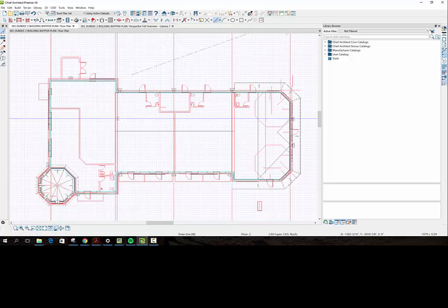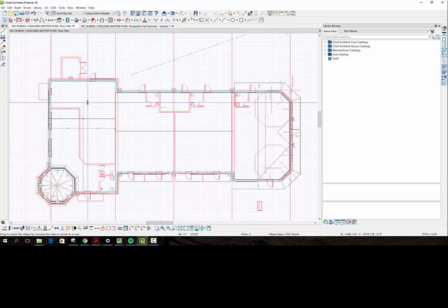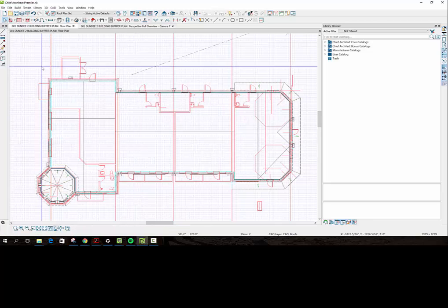So our truss is going to span from this to this. So we'll draw a line there. And that's the length of the truss. And we snapped it. See the snapping tools, Chief's snapping tools saying, yeah, you're here, buddy. And now we'll draw another line. And it should find the midpoint. That triangle's the midpoint. So that's the high point. So see, without dimensioning, we've gotten the high point just using the snapping tools.